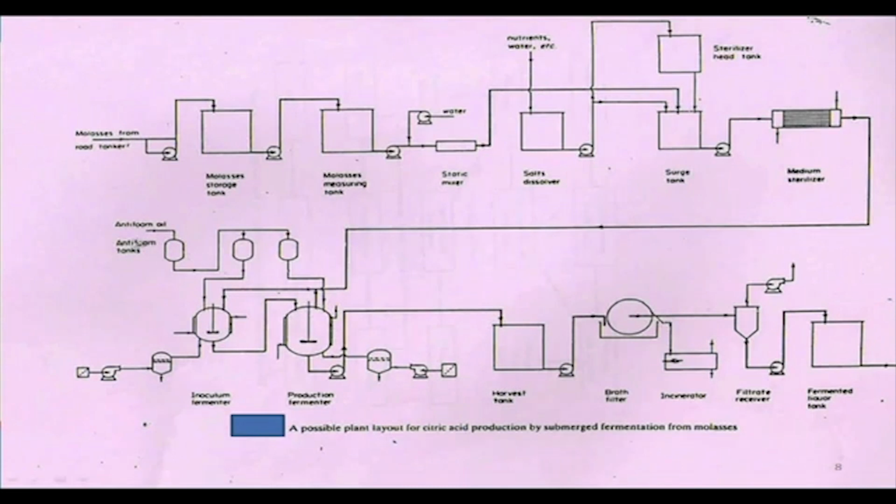And here you can see the antifoam oil tank. This has sterilized antifoam oil, which we use to subside the foam, and this antifoam tank is also connected with the mechanical seal. I told you when I explained the bioreactor, the shaft of this mechanical seal is also lubricated with the help of this antifoam oil, so that friction between the shaft and the mechanical seal is minimized.